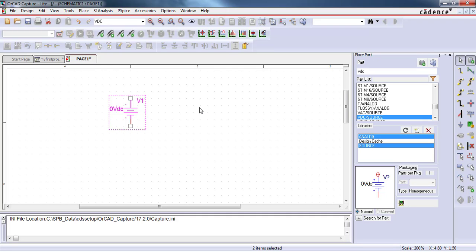Now to make connections we need wires. These can be used to make connections between parts. So let's choose a wire. Place it on one end of the source and drop it wherever you want by left click. To break the continuity, click the arrow or press the Escape key. You can delete parts by selecting them and pressing Delete on the keyboard.